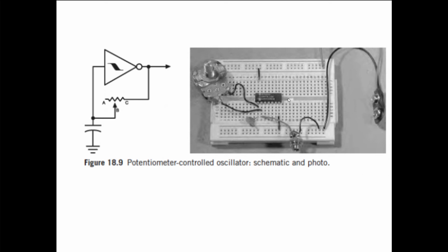The bottom pin on the left side of your IC package, always ground. The top right pin, always power. It doesn't matter how many feet that little bug has: 4, 14, 18, tons and tons. They'll all follow this convention.